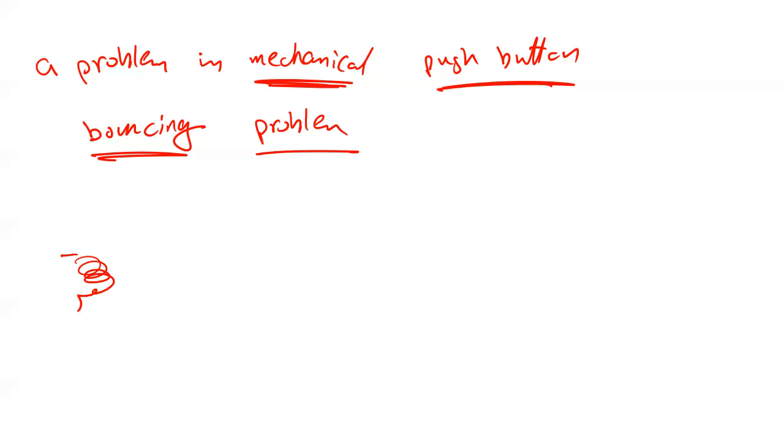You think if it's open, once I press, it's gonna connect right away. No, it's not going to work this way. Because it has a spring, it's going to do some bouncing. So this is exactly how it works. For example, it's open, and when I press, it's not going to make contact this way. No, it's going to make some bouncing before it settles this way, or remains this way. This is because of the nature of the spring. You got what I'm saying?